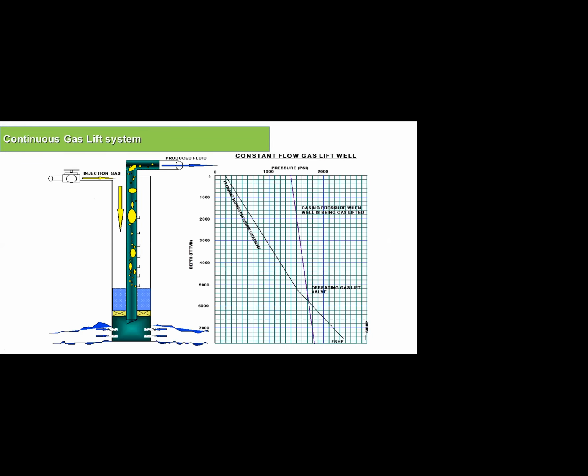So what is gas lift doing? As I mentioned, we inject high pressure gas here, it goes down, it mixes with the fluid coming from the formation, and then goes up. So how about the pressure? What happens? Normally we know that we have the pressure traverse curve, or the pressure gradient. As I move up, I must have a fluid gradient, like I have pressure losses through the wellbore.